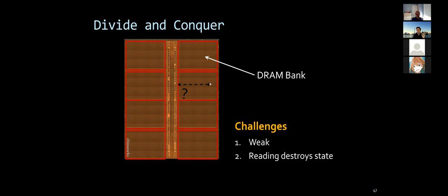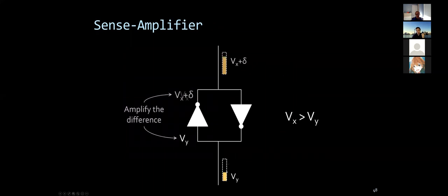It means I need to optimize. So they're faster to read, but they lose charge faster. So that creates some challenges. And again, the sense amplifier is another topic. That's the circuit we use to read the data based on the voltage. Essentially what the sense amplifier does is amplify the charge. When you read the cell and the charge goes down, in some cases it's higher than half and in some lower than half, and the sense amplifier amplifies the difference.